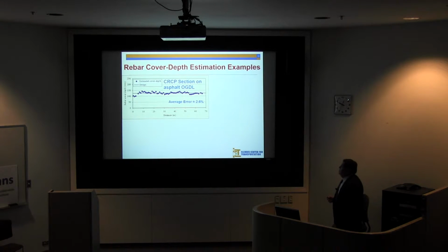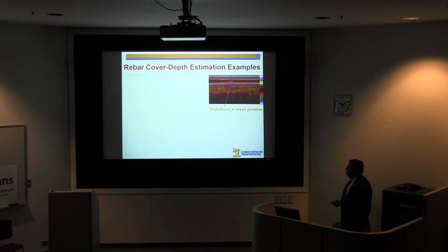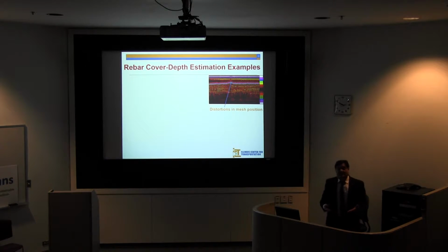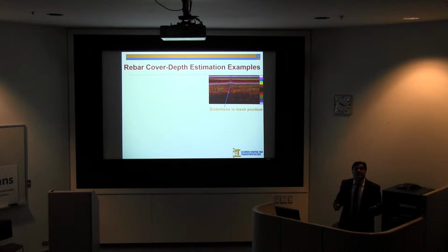And you can now accurately measure the cover depth that you have on top of the concrete, which is really important. Some of the rehabilitation techniques that we are using for asphalt concrete overlay is something called steel reinforcement mesh, or a mesh track, that we use in order to reinforce the materials to prevent or retard cracks from joints and underneath materials. So this technique here was used to detect where you have a problem during the installation that resulted in a problem on the surface.